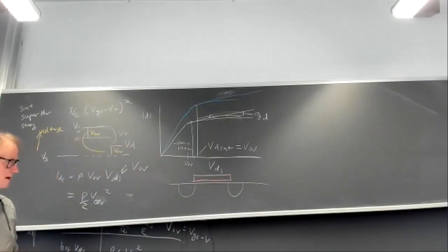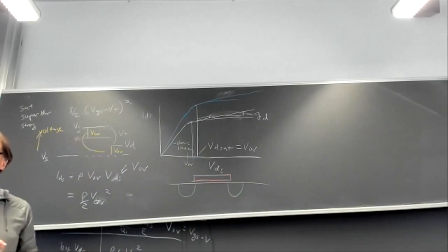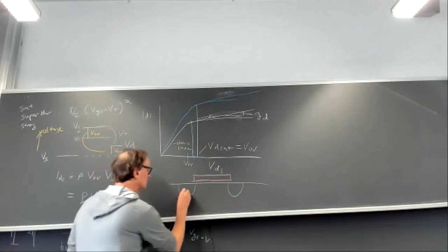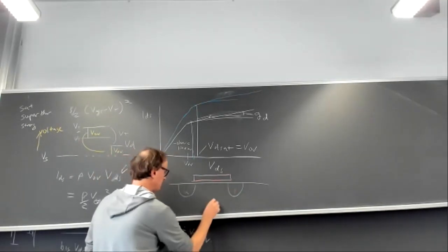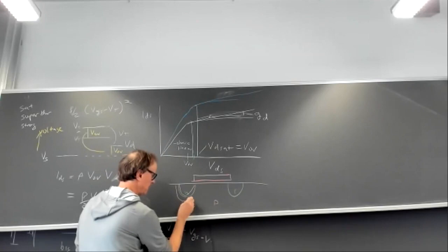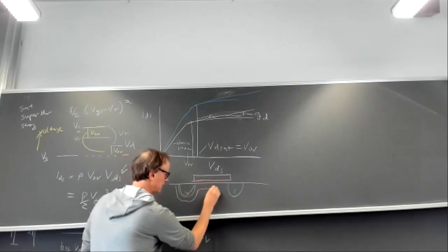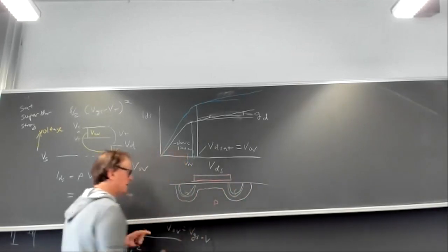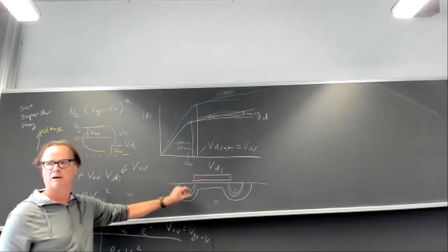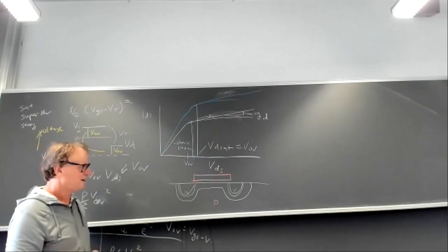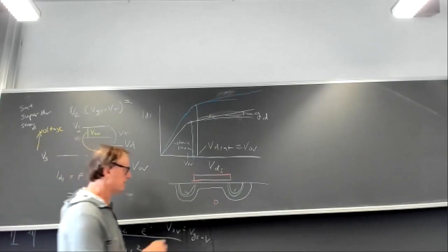Do you remember these depletion regions, these space charge regions you have at every PN junction? Actually, there's a depletion region around this N region, to this P region. I can draw this little depletion region, just draw it like this. It's actually a two-sided depletion region. And when you operate the transistor, of course, there's going to be a depletion region in the channel. There's going to be a depletion region around the drain, and it's a double-sided depletion region. Remember, you have the space charge region where it's positive on one side and negative on the other. Anyway, it's a space charge region where there's no mobile charge, just fixed ions. So what happens when you increase the drain voltage?